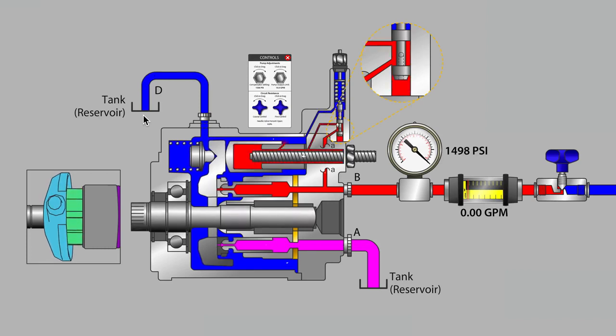And for a very high quality pump at very high pressures, that might be in the range of 5%. For some very large pumps, it could be up to 10%. And for some very small or very poorly manufactured piston pumps, that flow rate could be 15% or more. 15%, that is, of the pump's maximum output displacement for its regular flow. So it's not uncommon to see 10% of the maximum displacement of the pump present on the case drain line when we're at maximum pressure.